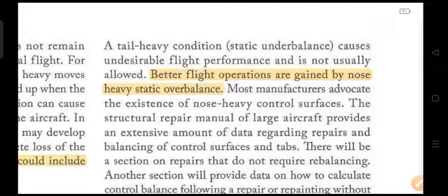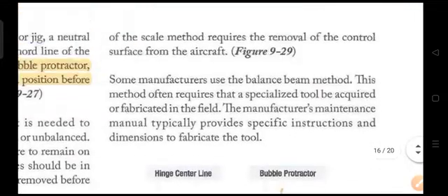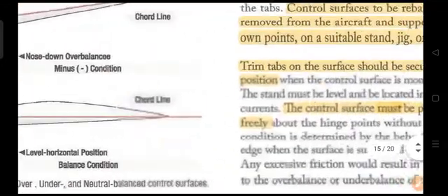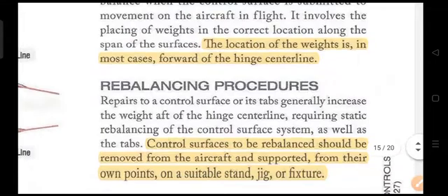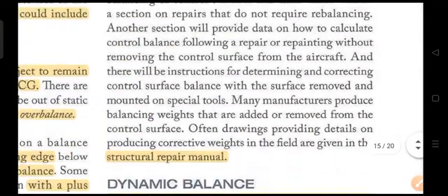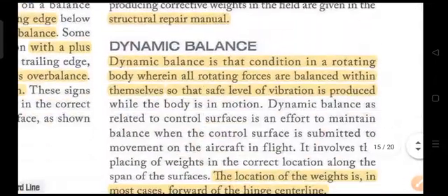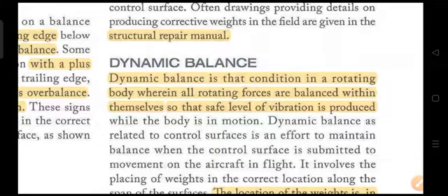So we have to keep in mind that a bit of nose heavy condition is always good. Okay, this will be there in the structural repair manual. All these works that you have to do will be in the structural repair manual, not in the aircraft maintenance manual. It will be in structural repair manuals, because these are all structural things.